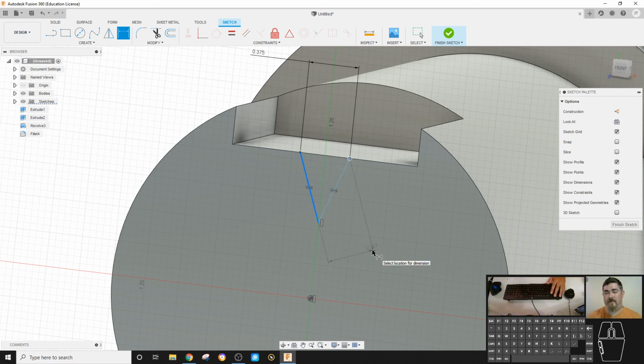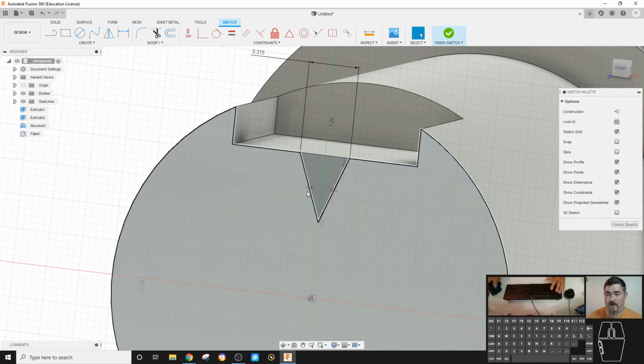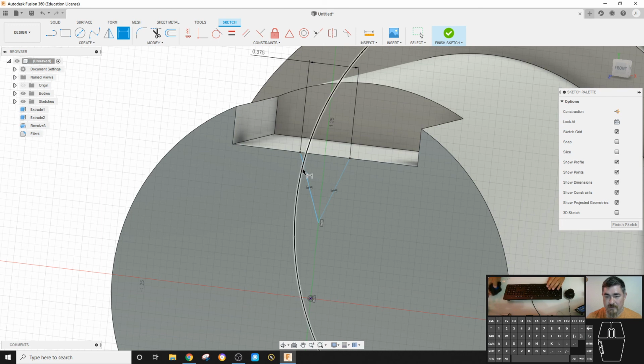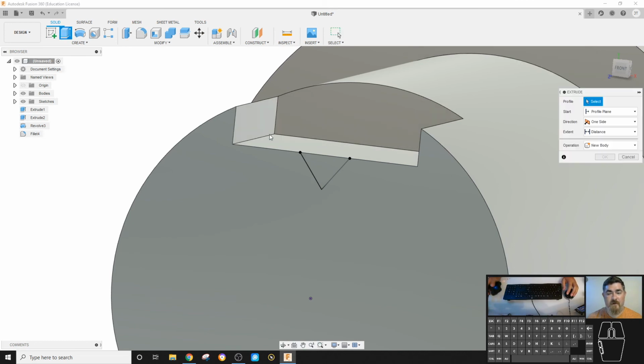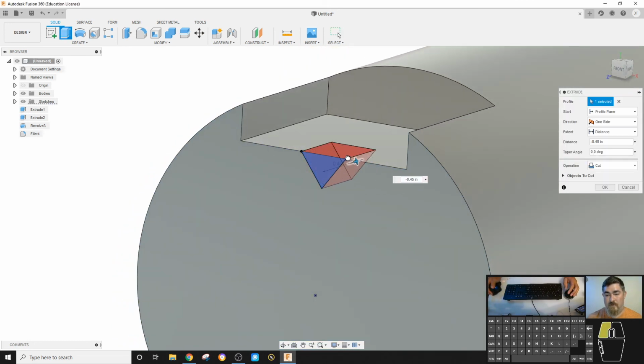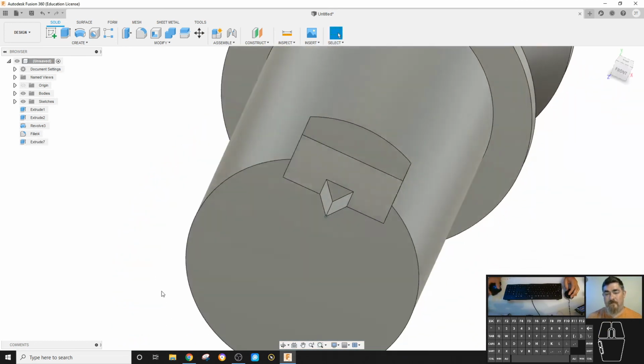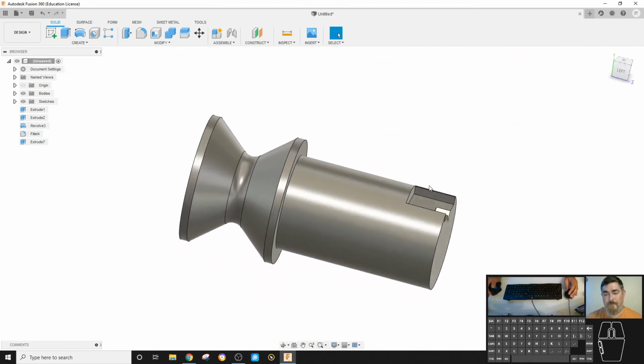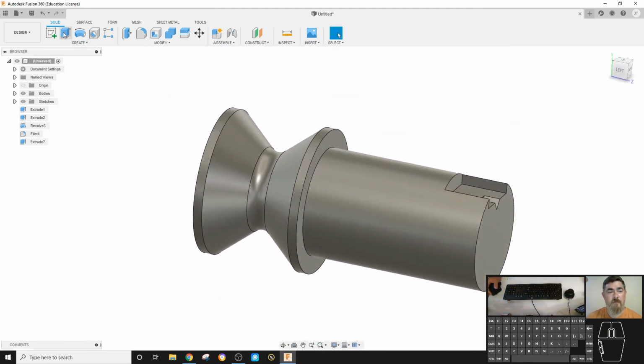And so knowing this helps you to kind of figure out, depending on how you want to dimension things, what to pick. So I could just pick this line and just go this way, tell it how tall it'll be, finish, extrude, cut back into it. Okay, so have fun doing those.